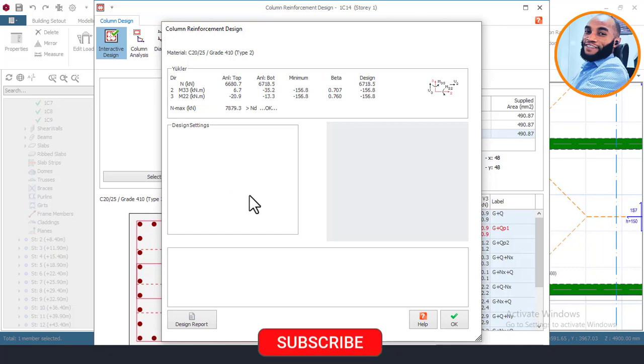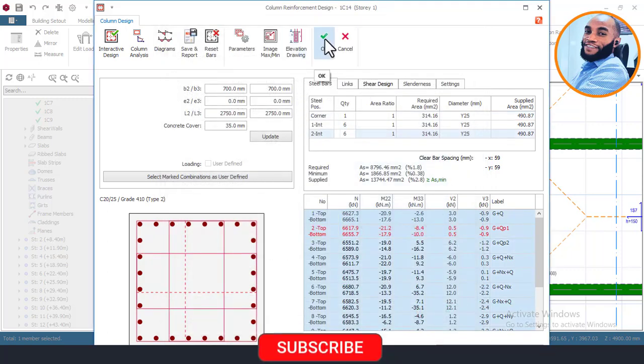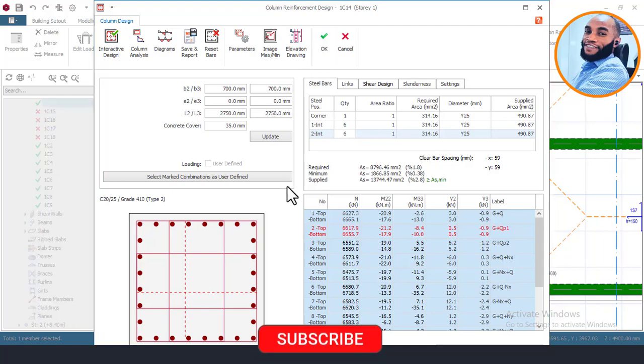Although it is safer, it is cheaper to increase the size of the concrete section than to use more number of bars. It is cheaper for the client to afford concrete than to afford steel. Okay, so I can use 700 for that. And then say okay and then okay. So while you're designing, also put into consideration the cost of the structure.